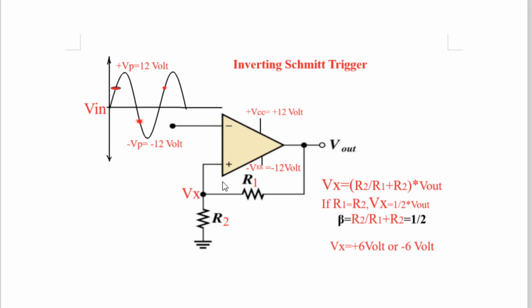And in this way, now this is minus 6 volt and the inverting input pin is now at 7 volt, 8 volt, 9 volt, 10 volt, 12 volt. So this is greater. Therefore, Vout will continue to remain in LVL, low voltage level. Now we want to see how long LVL remains at the output.